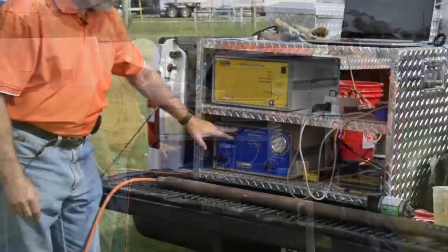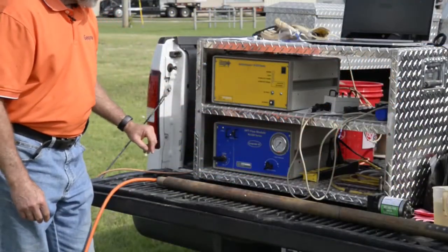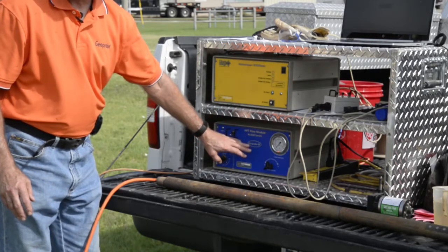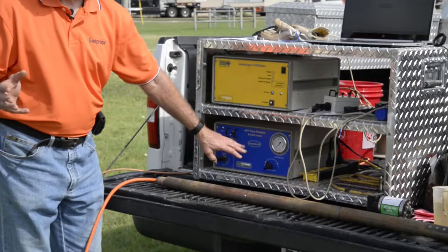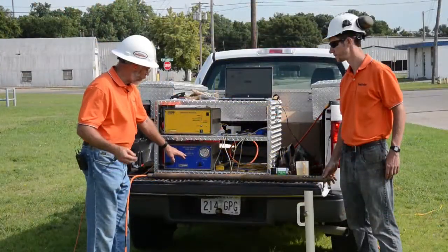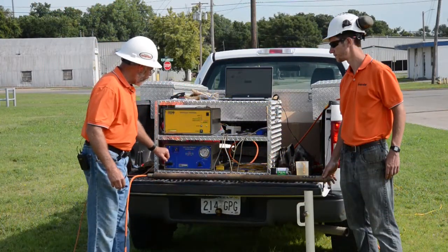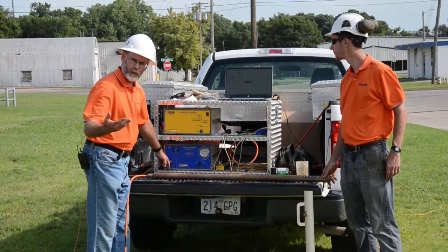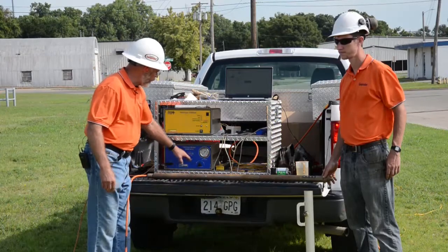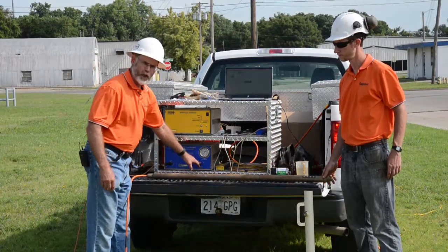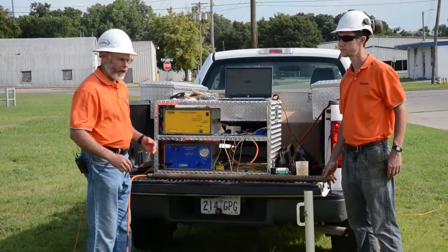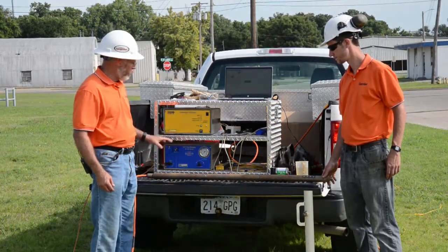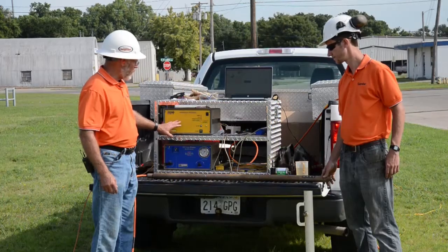Our HPT Flow Module here provides us with a pump for flow. There's a flow meter inside that shows us the flow rate if we're injecting the water into the formation. Okay. We also have an on-off valve for flow, so we can stop and do a dissipation test, which we should do later. And then we have a flow adjustment, so we can adjust our flow rate. And we typically run between 200, 300 mL per minute flow when we're running the HPT probe.